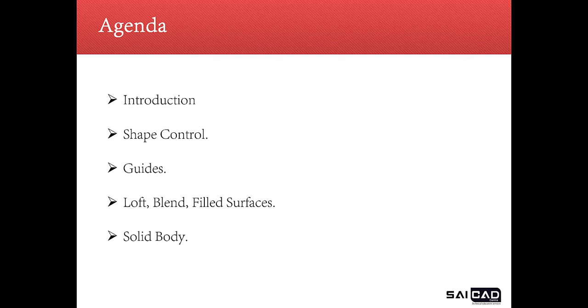Unlike solid modeling, your object can be geometrically and physically incorrect with no properties of mass defined and no thickness. This gives the designer the unique ability to modify the model in ways that solid models are incapable. This means, however, that surface models cannot be sliced open like their solid counterparts because the object is essentially hollow.